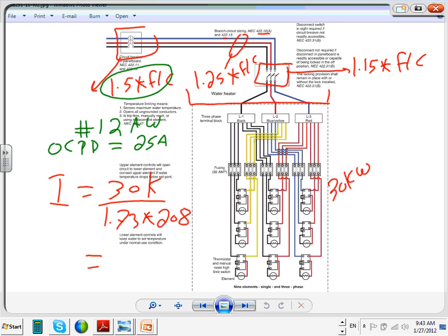You have two options. You can either lower this to 20 amps, but you're taking a chance that the heater might trip it. Okay? Most of us do the other option because it's safer, and they go up to what? Number 10. Why? Because number 10 is allowed by code to be protected up to 25 or 30 amps or less. This is only for appliances that don't have motors. If it's a motor, had this been a fan, what you have done here is perfect.